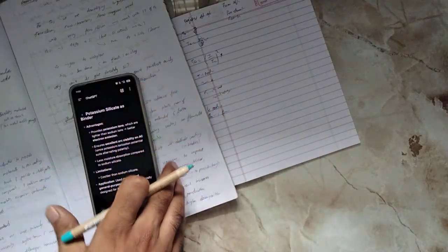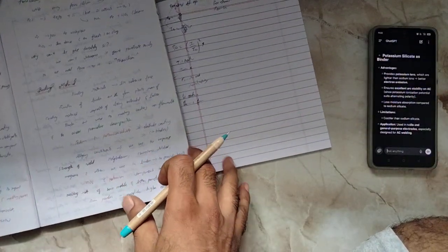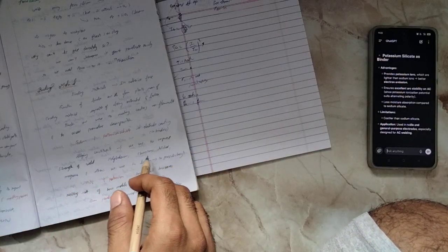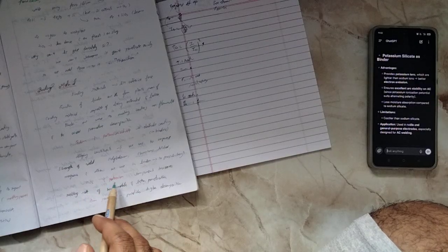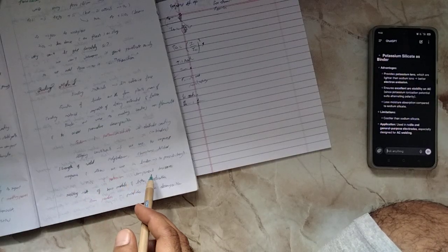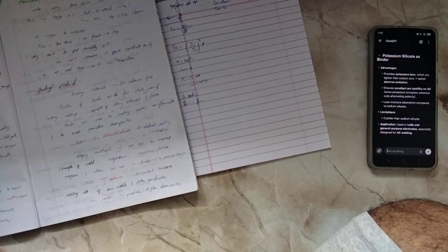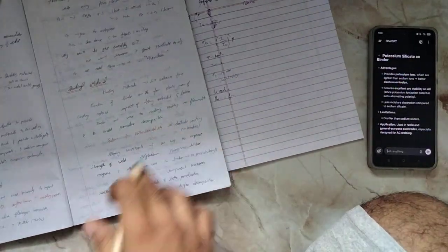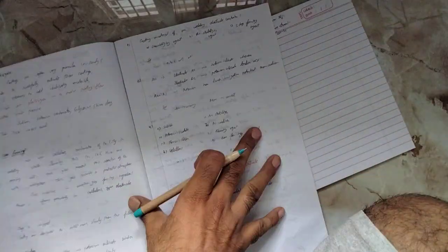I think you're able to understand. So the next thing you can see here, magnesium is used to improve the strength of welds, and this other element we are just studying. You can see titanium oxide and potassium components increase the melting rate of the base metal and give better penetration. Iron powder provides higher deposition. Generally they don't ask this kind of thing, but you just have to know it, that's it.